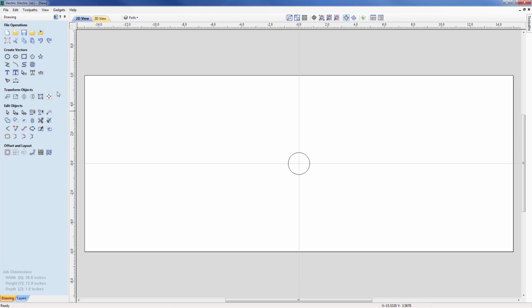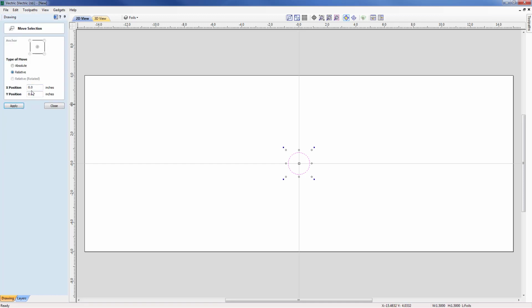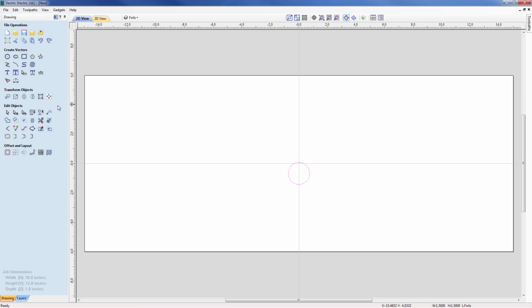And actually in this particular case I need to move this down. So with this I'm going to select the vector now and come across to the move selected objects command and just move this by a relative position, and it's going to be y, and it's going to be negative 2/3 equals, okay, and apply that downwards, and that will have moved that down by 2/3 of an inch. So with that I'm going to close out that form now,